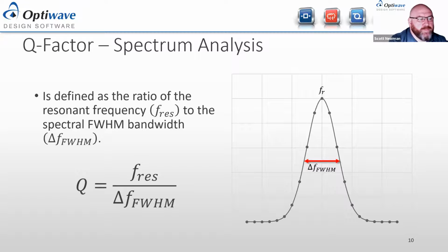Here's the problem with that though. With photonic crystal cavities, if you engineer them carefully, the Q can get very high, which means they hold the information there for a very long time, which means you need to run your simulation for many, many time steps, because otherwise you're just not getting enough information about the decay because the decay is so slow. This is obviously a problem in FDTD simulations, which are computationally intensive. And running them long enough for something with a Q factor of 1,000 is just not feasible.